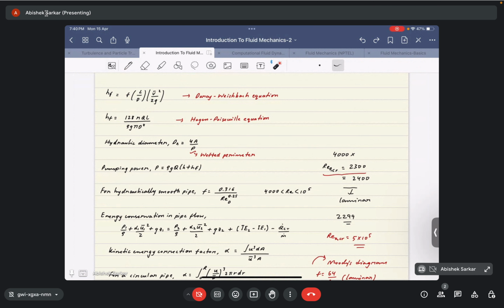And HF is also equal to 128 mu QL by rho g pi d to the power 4. This is the Hagen-Poiseuille equation. Okay, this is a very important equation. If you remember that one, you can easily solve problems related to pipe flows.